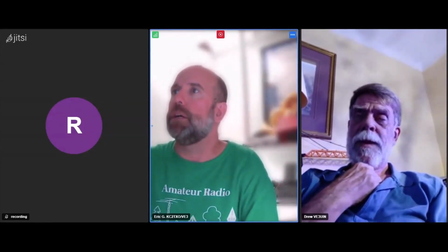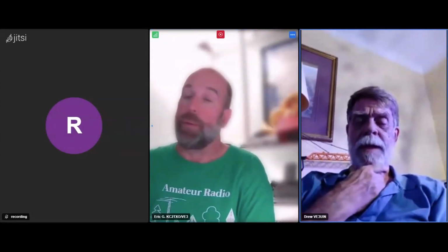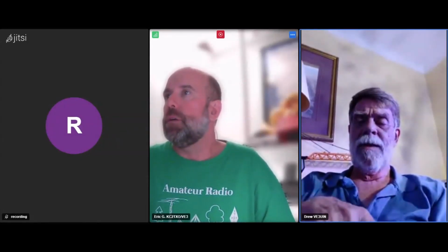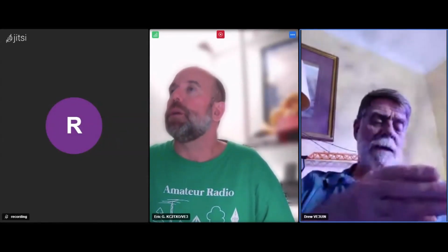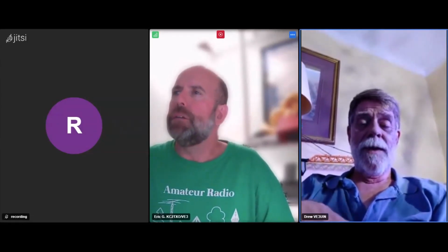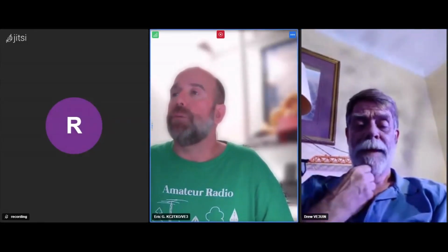I don't know about the RigExpert, I've never used one. With the NanoVNA you can sweep the frequencies and jump bands. You just tell it to go from like 3.5 to 14 and see where the peaks and valleys show up. Oh yeah, the RigExpert definitely does that.